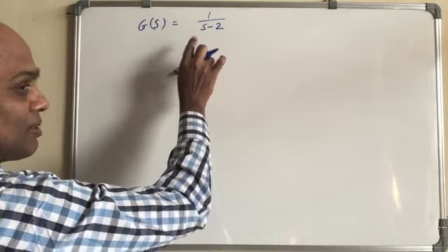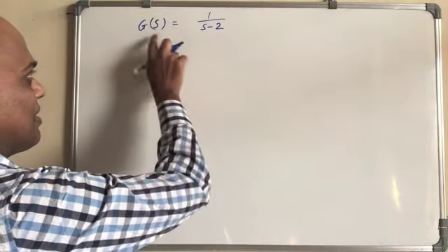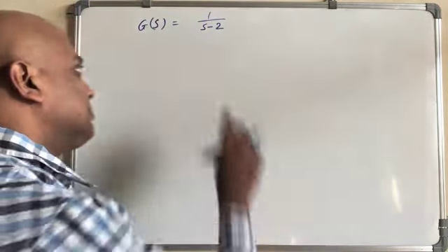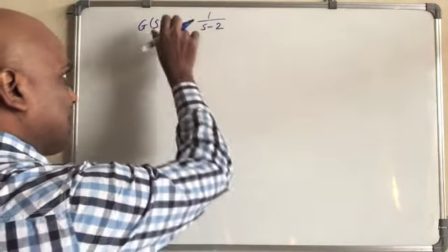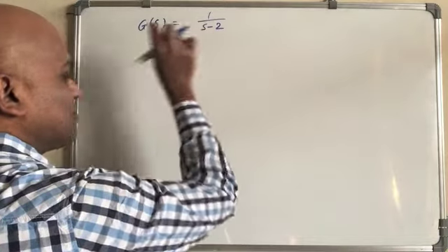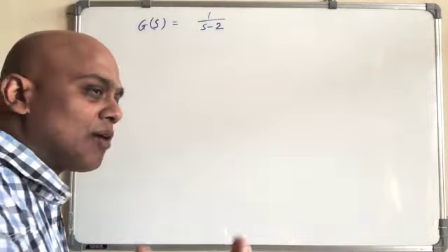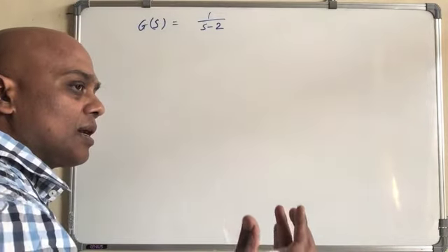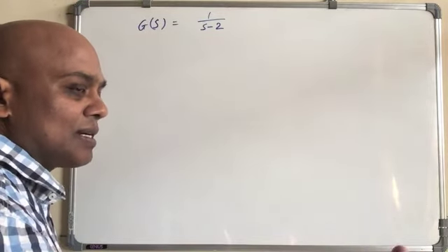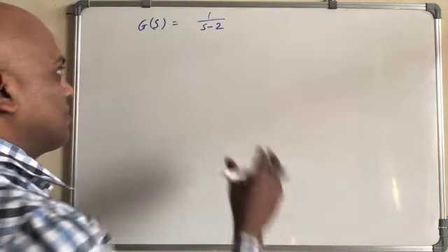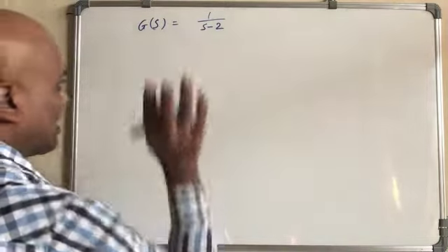That indicates basically if we make this the transfer function, any system which represents this will be unstable, right? So there is an interesting observation when you have a root on the right hand side, on the right half of the S plane. So let's understand that.